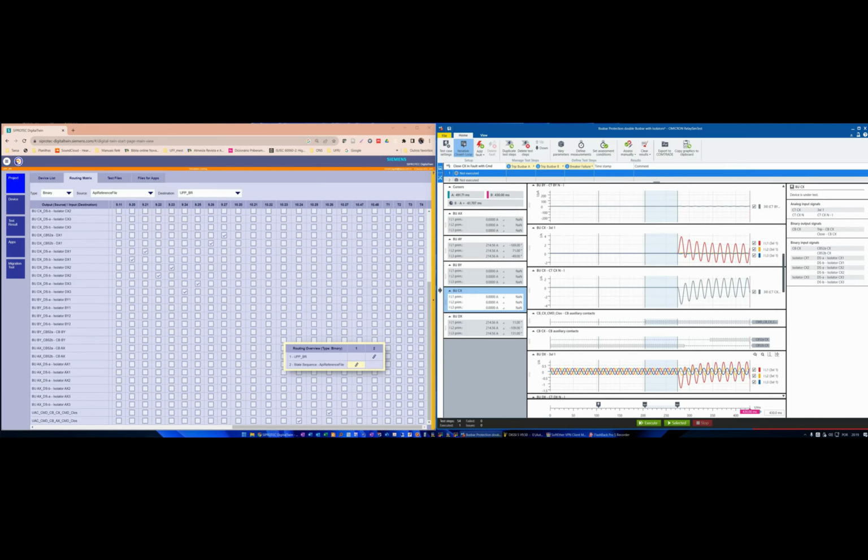And we can see here the circuit breaker will be closed because of this step of the simulation. And I put a time between my command and the close command of the circuit breaker. We can set this time here, for example, I put a delay to the previous event of 70 milliseconds.